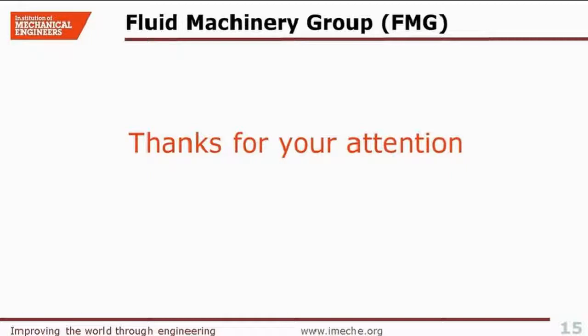Pump A had much higher operating hours compared to pump B, so it is very obvious that if there was a risk of suction recirculation, pump A was exposed to more operating hours, and as a result there would be more wear and tear in the pump.